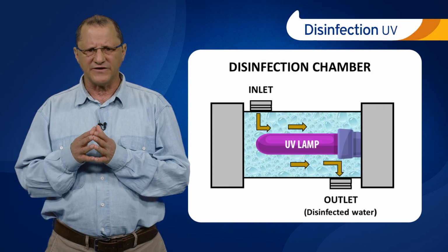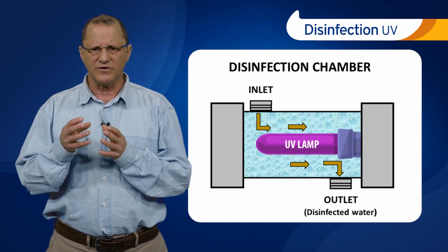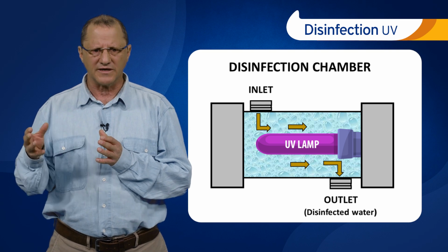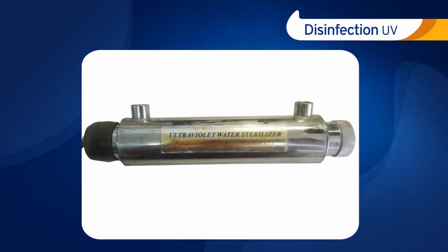When using UV disinfection, the water must be exposed to the UV light long enough so the UV dose that corresponds to the lamp's energy and the contact time are great enough to disinfect the water. Typically, flow-through UV lamps such as in the picture are used on-site. It should be noted that the membrane technology for wastewater treatment that is discussed in the course is becoming more commonly used, but it's still too expensive and sophisticated for widespread on-site use.